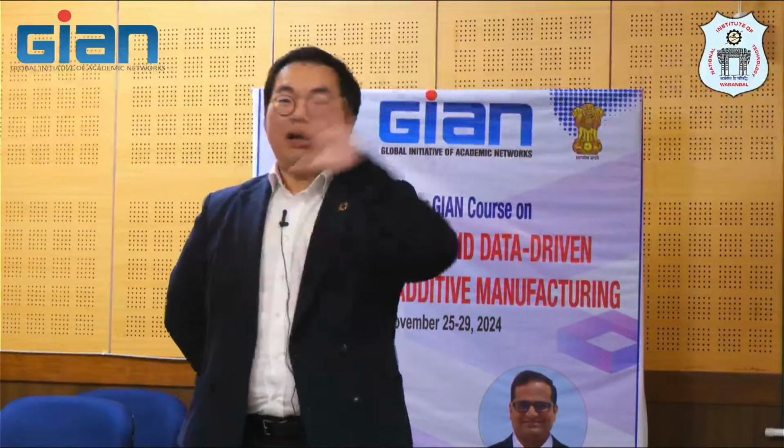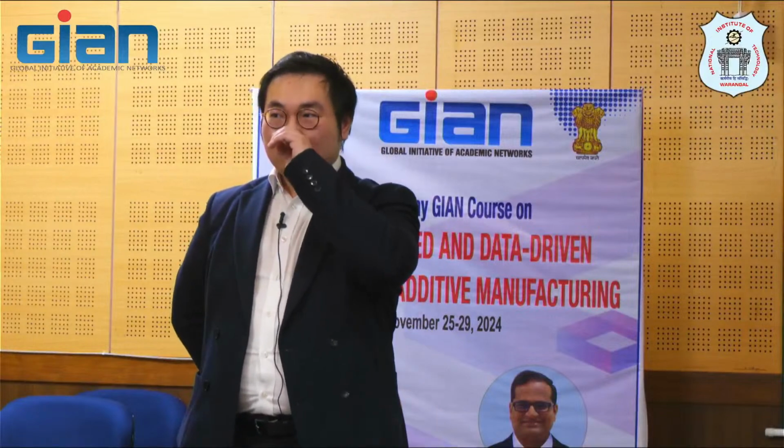During which heat treatment time are you preferring to have the gamma prime segregated? Yeah, that's what I said. We call it print soft, and then we recover the strength later, or harden later. At the time of printing, it is solid solution. It can cause cracking and all, but later, no. At the time of printing, if gamma prime is precipitated, it can cause cracking, right? At the time of printing means when we are printing the samples. If it's solid solution, probably less likely.